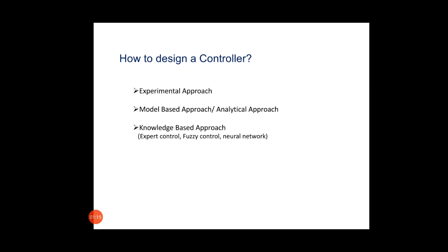see and get the parameter, so that the control variable follows the command to an accuracy acceptable to the process engineer or user. This particular experimental design is referred to as controller tuning. This is the method which is extensively used in process control applications, because the requirement there, first, is that the information about the process is not available so as to model it accurately.